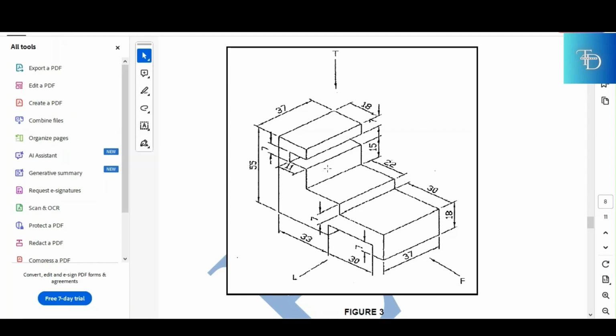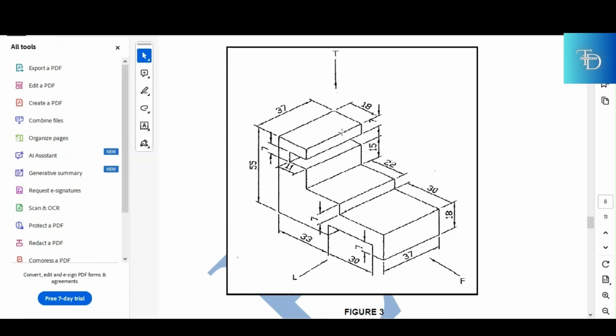Now, before you confirm that this is the fourth and the last surface, that's actually wrong because you have that surface there. That's like a groove right there. It's inside, but it's still parallel to which surface? To this one. It's in a rectangular shape, just like all the other surfaces. And then goes the last one. So basically what you're gonna see when you're standing at your front view, you're gonna see rectangles stacking on top of each other all the way up to the top side. So that's what you're gonna see. So you take it as it is, you take the dimensions, you transfer it to where? To the space where you're supposed to put your front. Now let's go and do that.